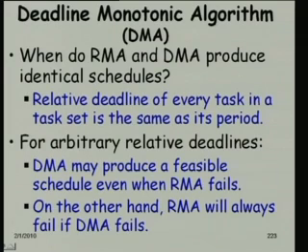No, that is what I have been trying to tell. To start with, we had told it in very simple words that the rate monotonic algorithm is an optimal algorithm. What we left unsaid is that when the deadline and the period are the same, it is the optimal algorithm. We left it unsaid just for simplicity, but now we are slightly making it more complicated.